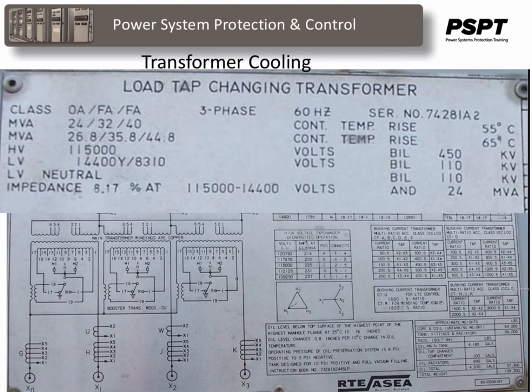Again, the mechanically assisted equipment is usually automatically switched on as the operating temperature rises, but it could be operator initiated as well. In either case, close observation is still required, as this piece of equipment is operated close to the rating limits. In any event, protective relaying should take it out if limits exceed a temperature rating for too long.